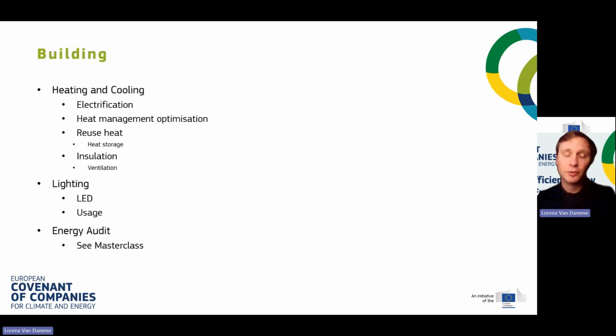This could mean that, for example, your building has a centrally controlled heating system that is maybe at this point heating up the building, while there are some separate air conditioning units available that could cool down specific rooms. It would be a good idea to check that you don't have these systems that are in conflict with each other, where at the same time a room is being heated and being cooled, because this is, of course, a waste of energy.